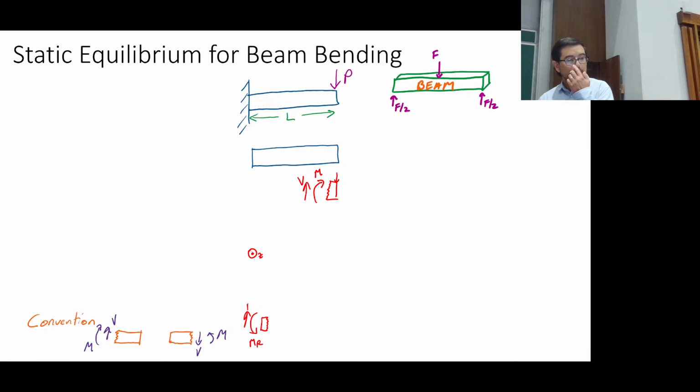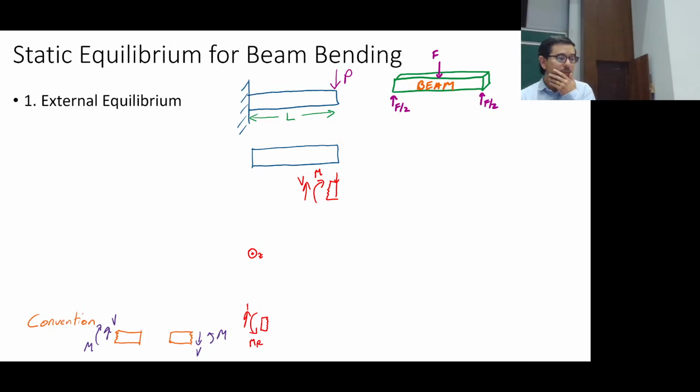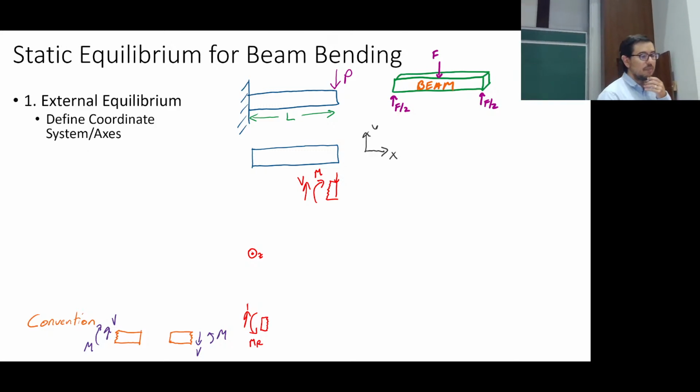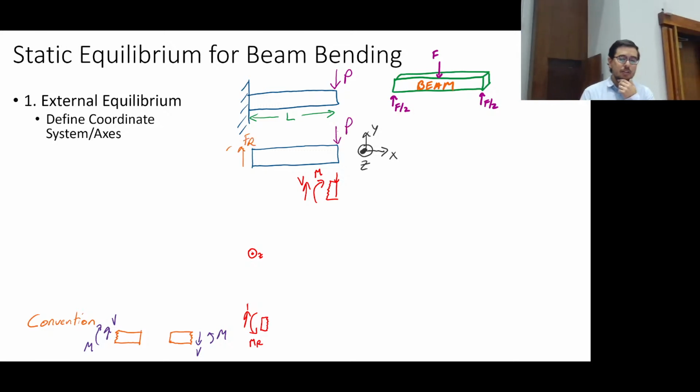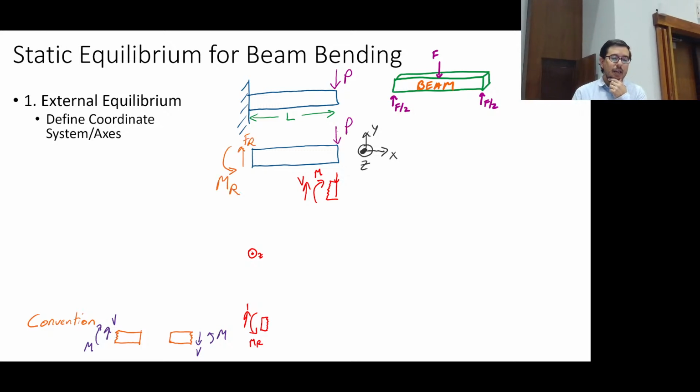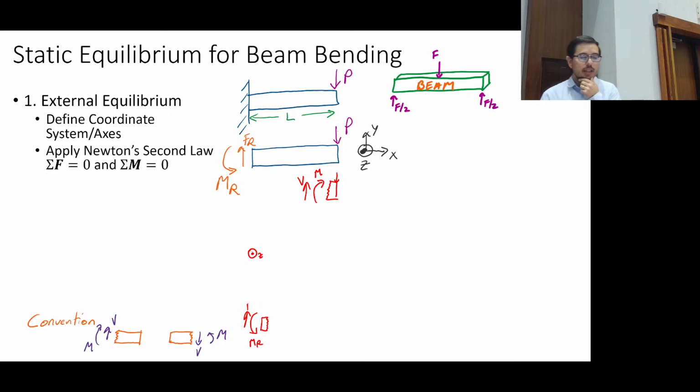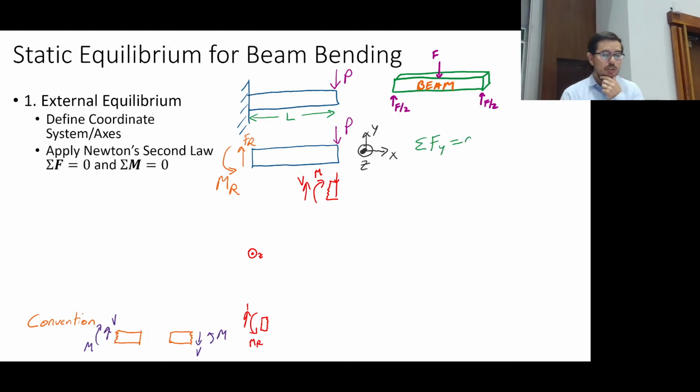What do you do? First, external equilibrium. Define the coordinate system, and then apply Newton's laws. Okay. Second, we're going to take a slice.